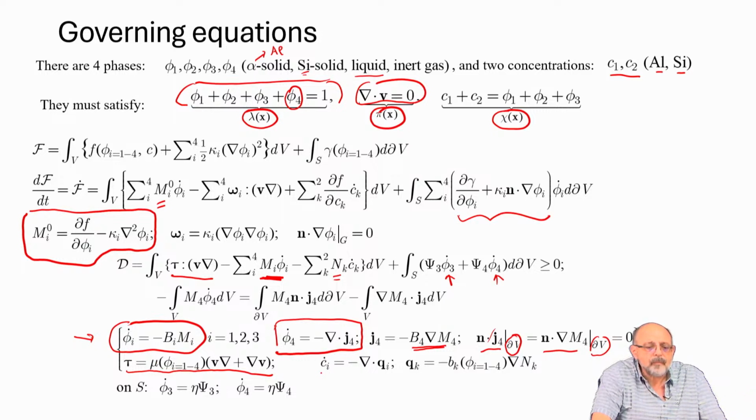So now, my diffusing species are conserved. My aluminum alpha phases and silicon solid phases are not. But my species, aluminum and silicon, are conserved. So there are mass fluxes or atomic fluxes which have their own potentials, and they are proportional to those potentials, and those potentials are generalized forces that do the work, expending power on the rate of change of concentrations.